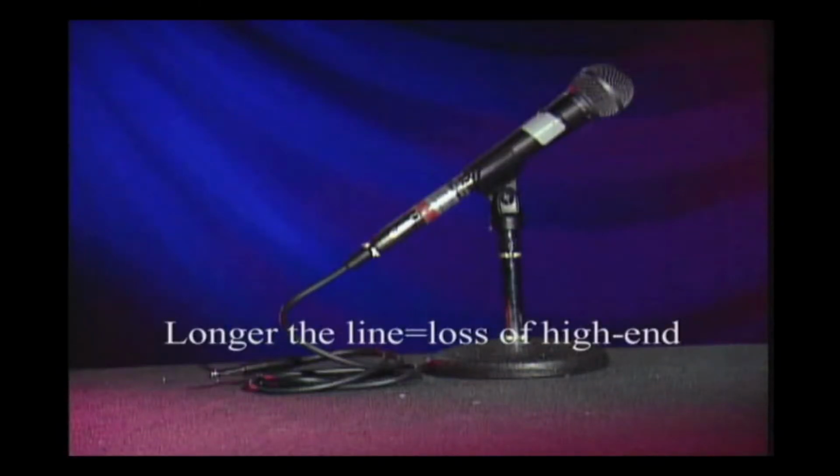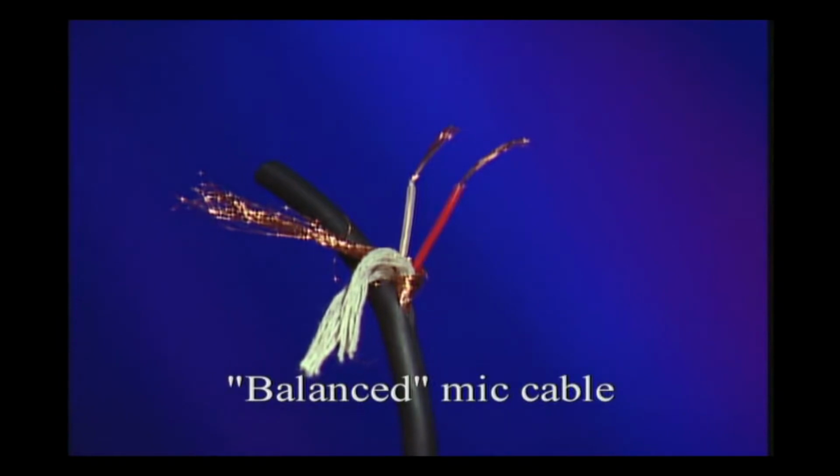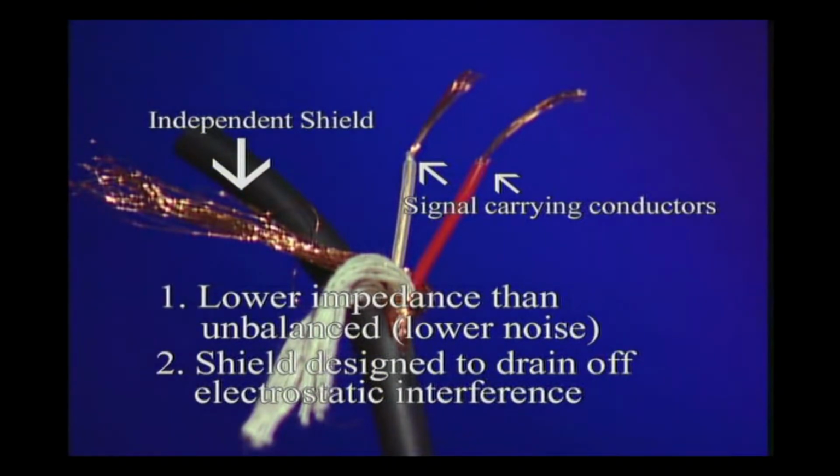The second disadvantage with unbalanced cables is the longer they are, the more noticeable the deterioration of high-frequency response becomes. This can be compounded by the high-frequency buzz to which this cable is already susceptible. Balanced cable, on the other hand, has a lower impedance than unbalanced cable, and it's designed to allow the shield to drain electrostatically induced currents independently off the signal-carrying conductors.